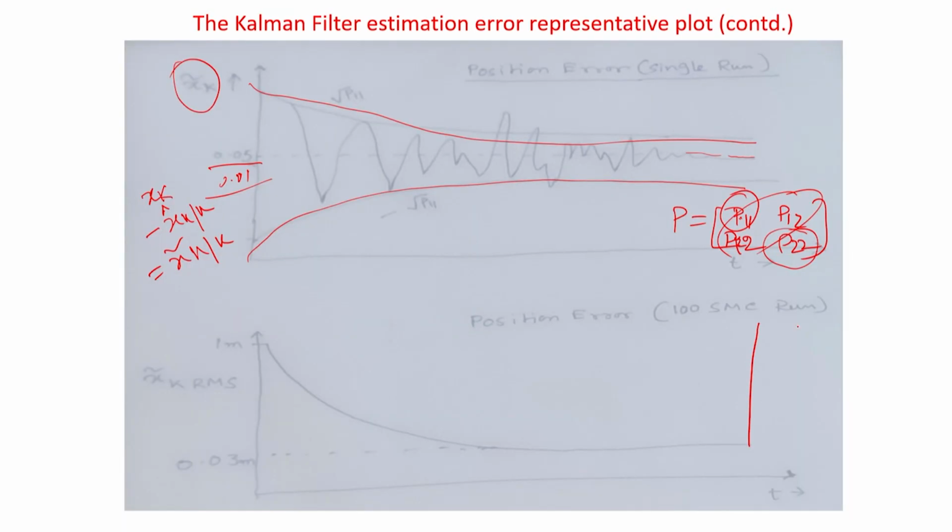So, it is like this. Your x tilde k|k, your estimation error, this is say sample 1, sample 2, maybe, and then the dots, say sample 100. With this you calculate the errors. So, this is say E1, E2 for each and every state, and say E100, say you have taken 100 Monte Carlo runs. By changing the seed, you simulated each and every measurement and you have collected the errors for each and every sample. So, you have a matrix for each and every state.